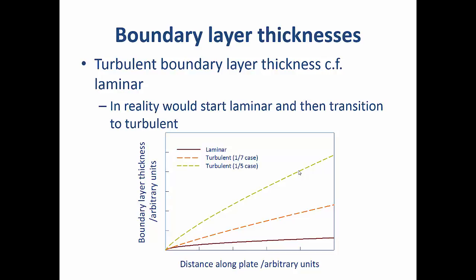And the other thing that you should remember is that in many cases the flow would strictly start laminar and then transition to turbulent. So right at this left hand end we shouldn't be using the turbulent results, we should be using laminar results and then allowing the turbulent results to develop.